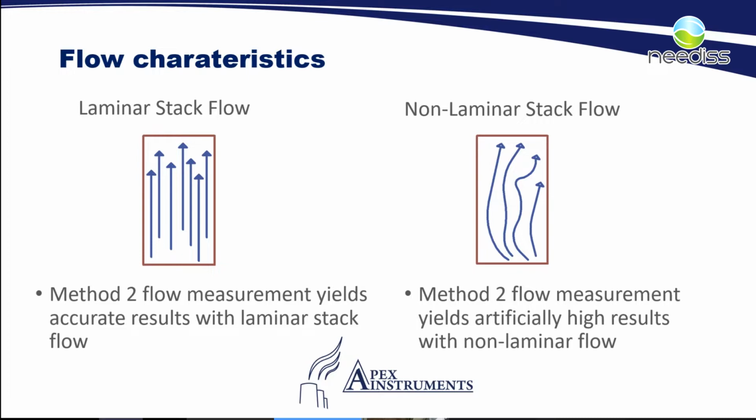And as you can see, the non-laminar flow is anything that is not coming straight up. So it may be going back and forth, zigzagging across the stack, or it could be cyclonic flow, which is going around and around the stack as it goes up to the top.